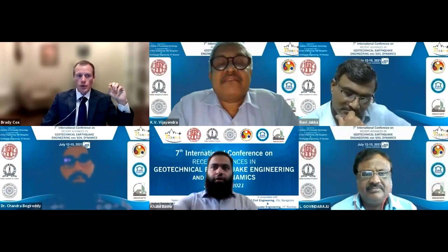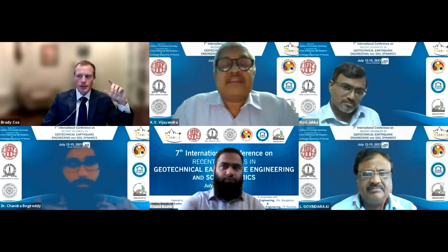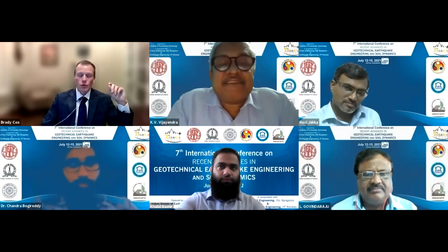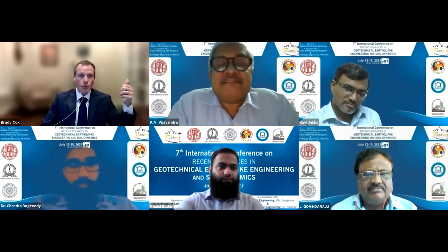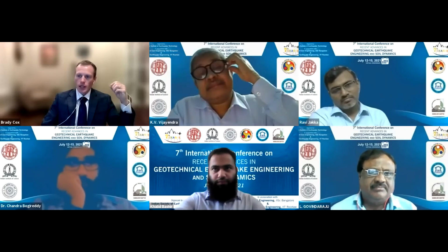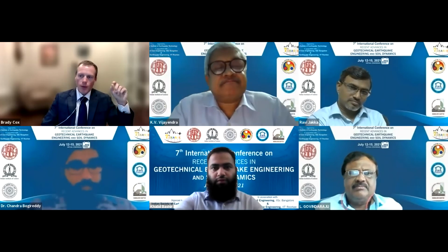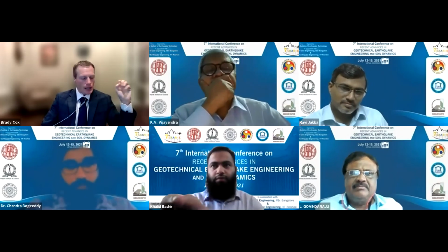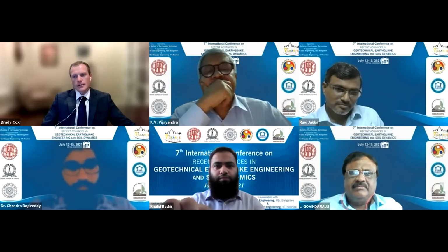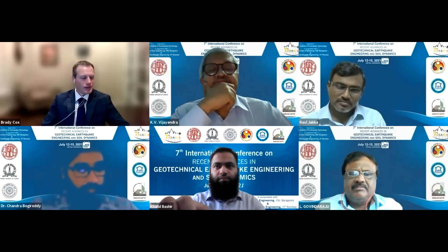And so in cases where the velocity profile is more complex, you might have to spend a little bit more time making sure that you use, for example, boring logs to help constrain what you're doing using knowledge of local geology. And for an inverse, low velocity layer, you're probably going to have to be a little bit more careful because that's a situation where things may not be as simple. So, as in all things, there are simple cases and there are complex cases. And in the complex cases, you're just going to have to be a little bit more careful.